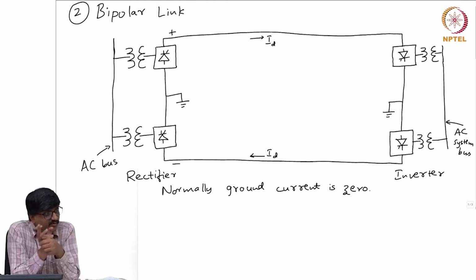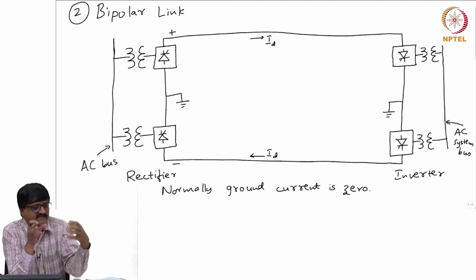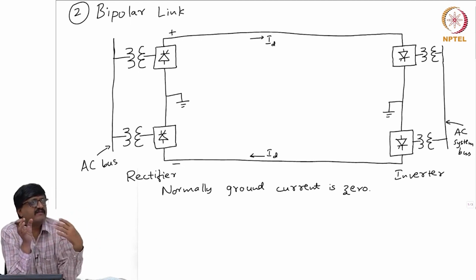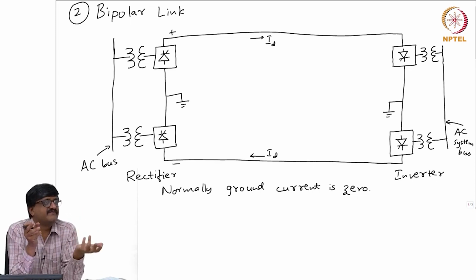Now, when it comes to one more transformer, there is Y delta. What I do here is assume that the Y delta transformer can also be represented by the same inductive reactance corresponding to leakage, and another set of voltages. The only thing is, the two voltages are identical except for what? Phase shift, that is all.